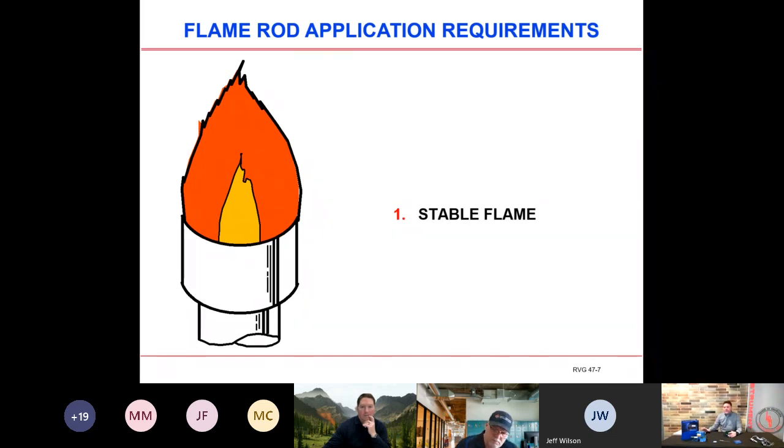So what it's actually doing is adding grounding surface to the flame rod itself, and it changes that 4 to 1 pretty dramatically. And when it does that, it starts dropping that voltage signal back to your flame relay to hold in for that flame circuit.